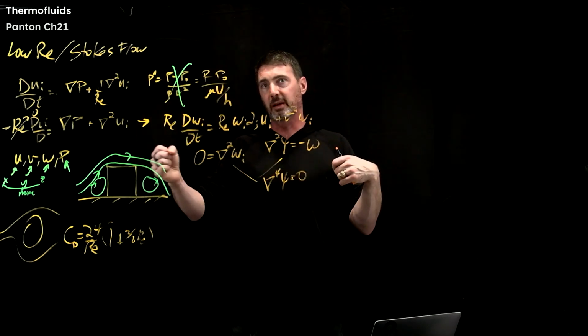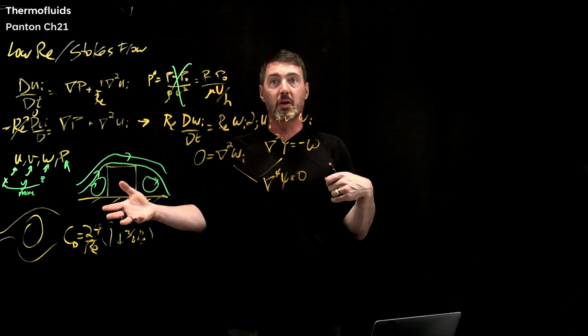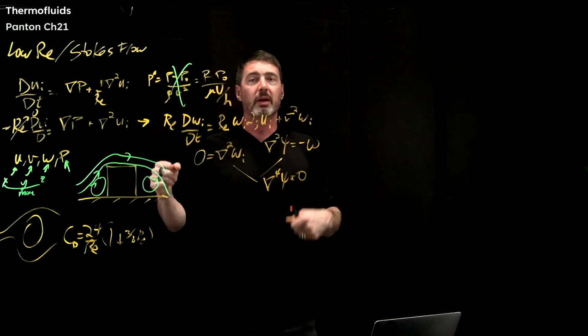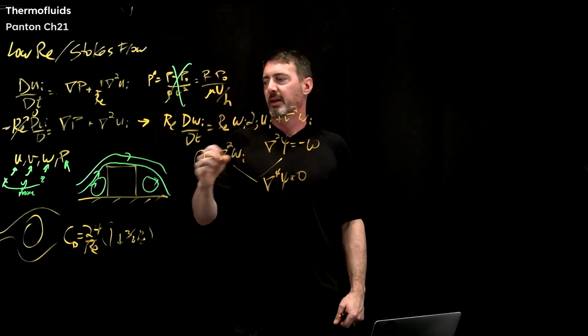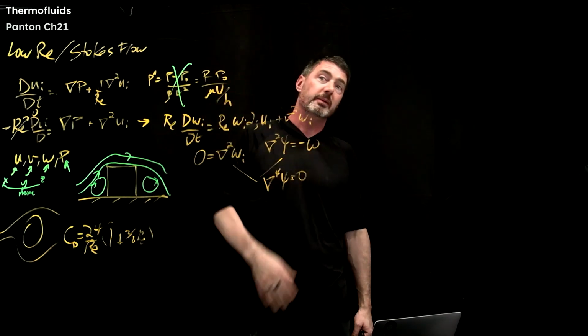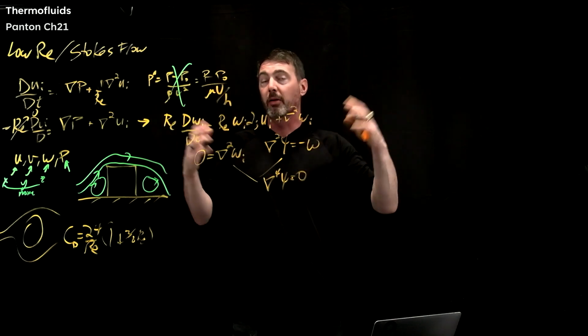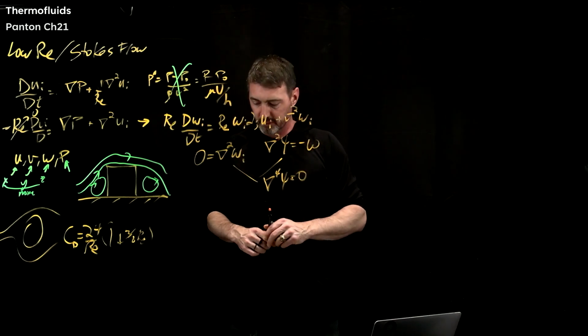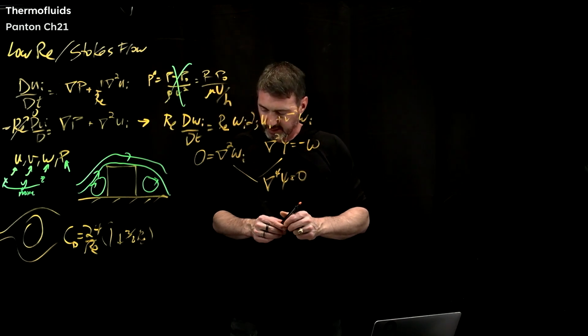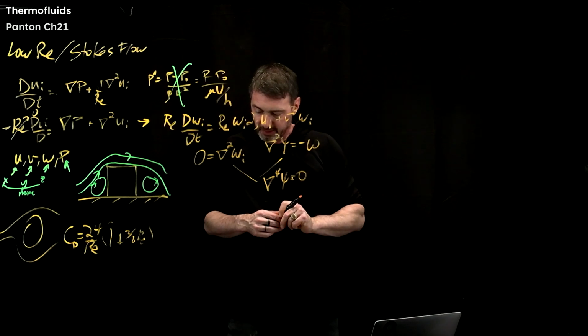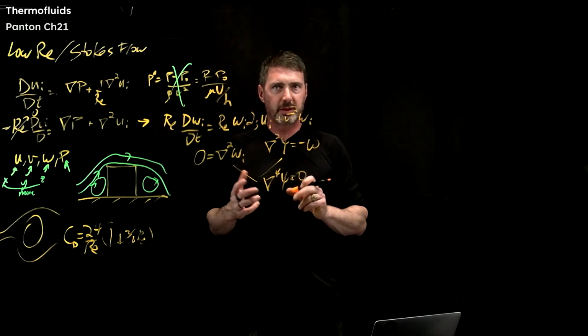You have to pay attention to how you seed your flow, and make sure it's a Stokes flow so that the particulates are basically just getting carried by the air or water, whatever you're doing your flow visualization and data acquisition on. Okay, so that's pretty important stuff.